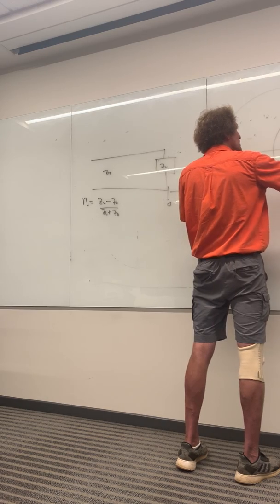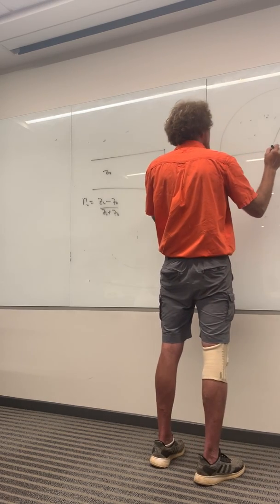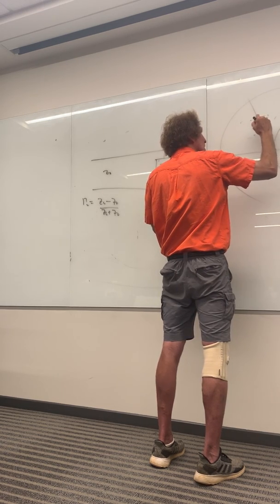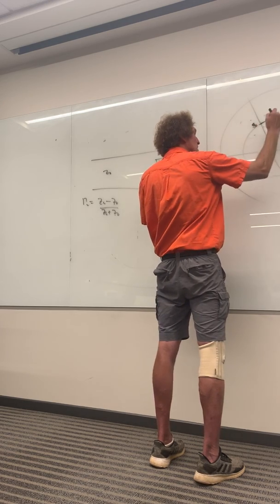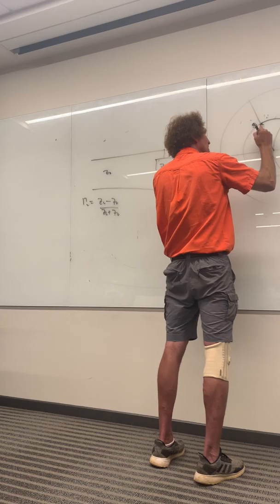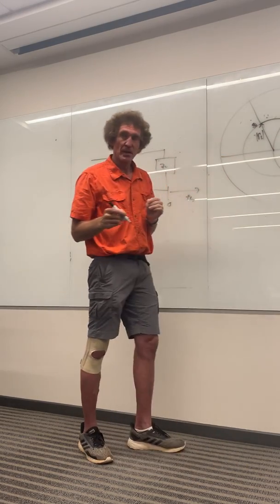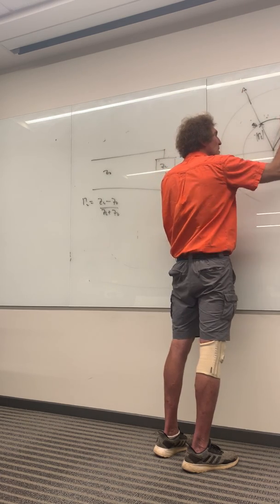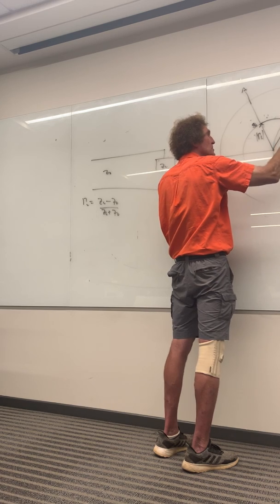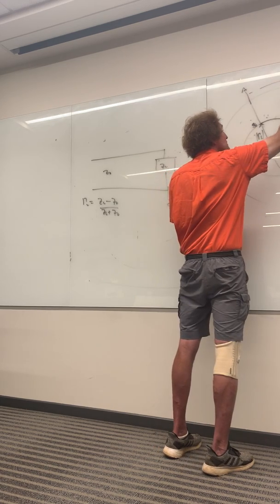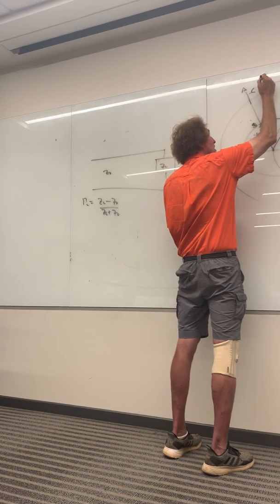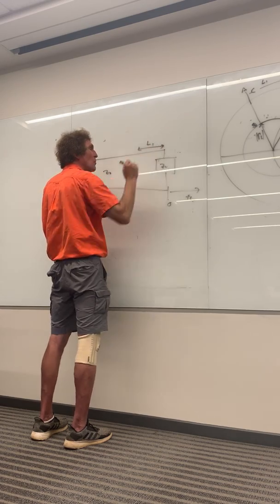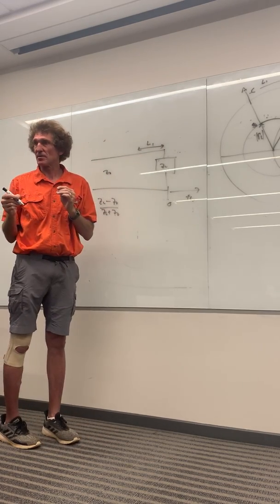And that's the R equals 1 circle. So if we come in and we plot ZL here, let's say this is my ZL normalized, and I'm going to draw this like this. That's ZL, and this is the reflection coefficient's magnitude, that's the radius of that circle. When we move from this point, whatever it is, point A, to this point, where this circle intercepts the R equals 1 circle, I move a certain distance. I'm going to call this right now just L1. So I'm moving wavelengths toward the generator that distance, all right?